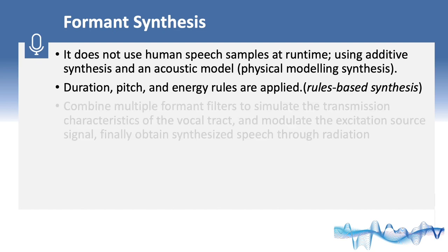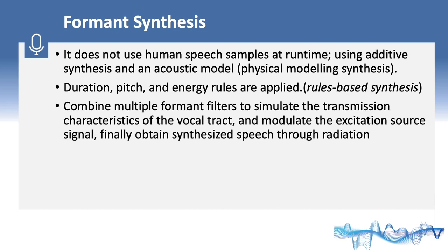Formant synthesis combines multiple formant filters to simulate the transmission characteristics of the vocal tract and modulate the excitation source signal. Finally, synthesized speech is obtained through radiation.